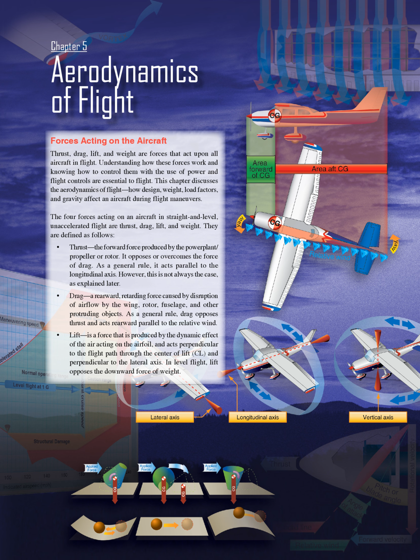Chapter 5: Aerodynamics of Flight. Forces acting on the aircraft. Thrust, drag, lift, and weight are forces that act upon all aircraft in flight. Understanding how these forces work and knowing how to control them with the use of power and flight controls are essential to flight. This chapter discusses the aerodynamics of flight, how design, weight, load factors, and gravity affect an aircraft